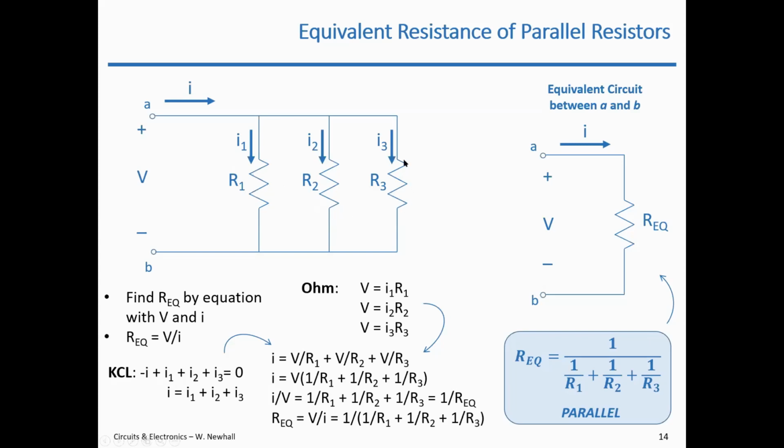I'm not even showing it here. I don't want to even get it in your head, but they'll apply that to 3 resistances, and you get the wrong answer. This equation always works no matter how many resistances you have. If you have 4 resistors, just add plus 1 over R4 in the denominator. Okay, so I would recommend using this.